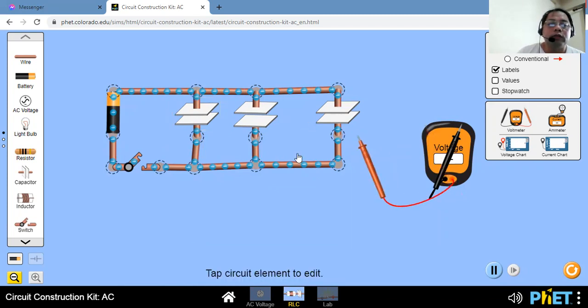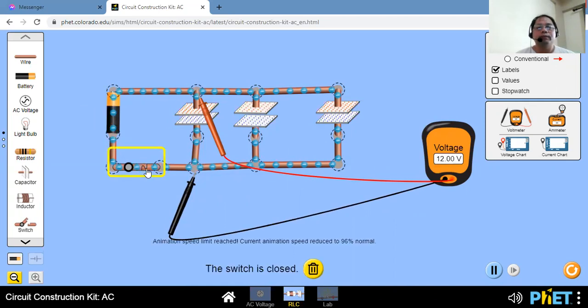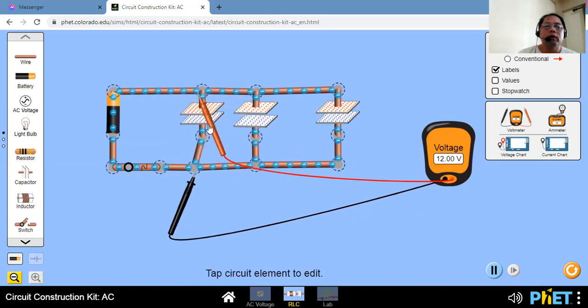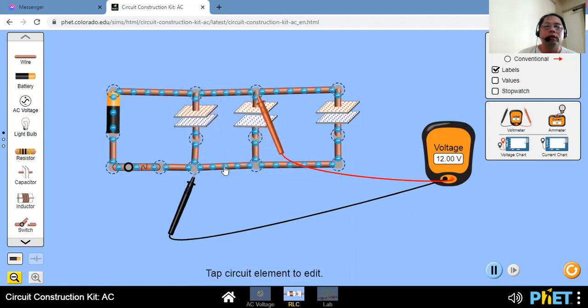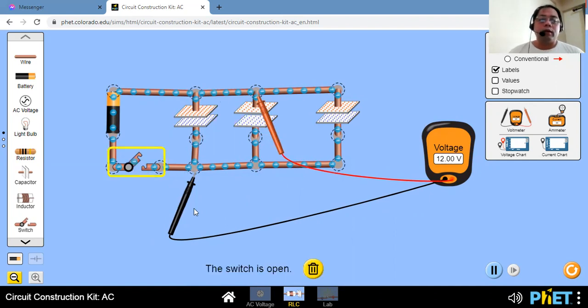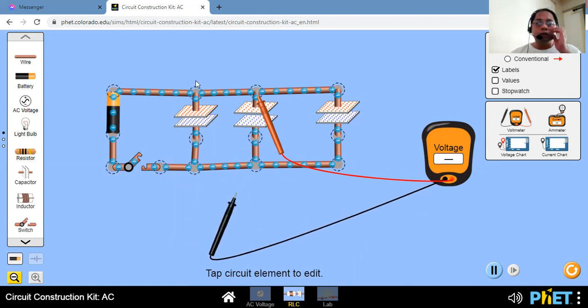Now, for the value of the voltage, you can now place the terminals of your voltmeter here once you turn on your circuit. So once the circuit is closed, you'll see that you can now get a reading for the voltmeter. So this is how we could get the voltmeter value. So this is our V sub 1 when we position the voltmeter here.